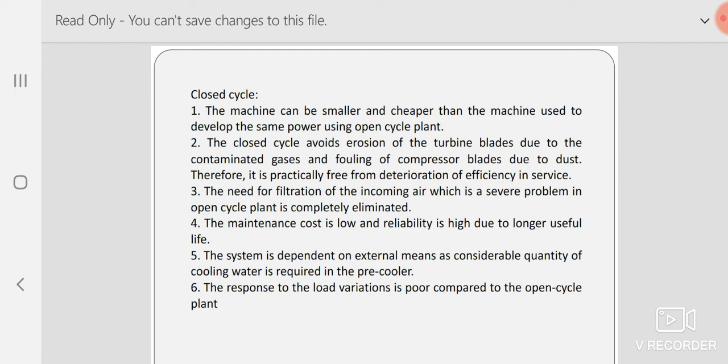The higher the level of filtration, the higher is the suction force required in the compressor. The higher the suction force required in the compressor, the higher is the power required in running the compressor shaft. That means higher is the input of the compressor and the output is less. That is, the efficiency of the compressor goes down. And higher input of compressor means higher loss of power from the turbine, because the turbine shaft rotates the compressor. Higher loss in the turbine shaft means less power going to the power plant, which is my main intention.